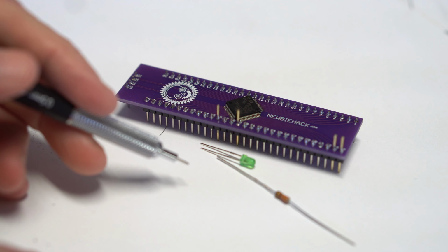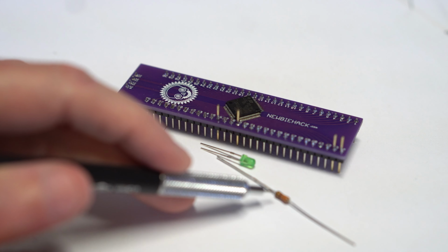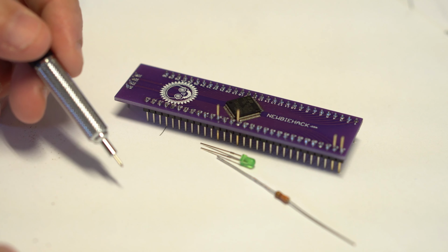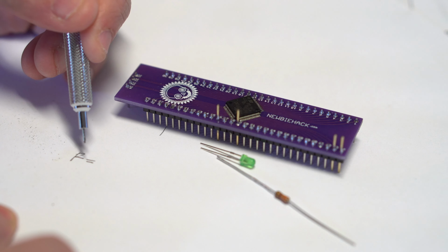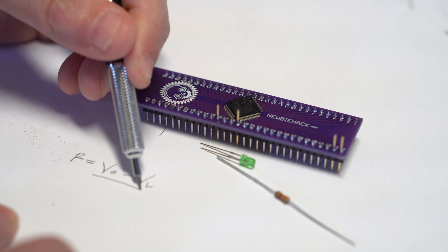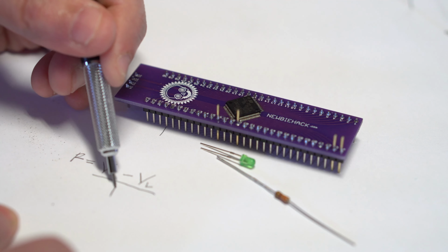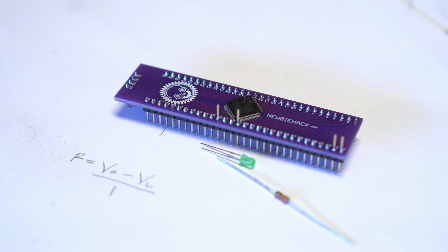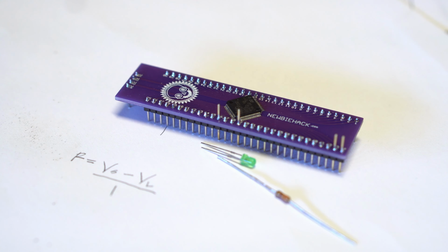If you want to figure out the actual resistor you need to use, you can figure that out using this formula. The resistance is equal to the supply voltage minus the LED voltage, which you'll need to know, divided by the current. I lost sound at this point, but if you use 0.01 amps for your current, which is a conservative number, the supply voltage is 3.3, and I use 2 volts for the LED voltage. You'll have to look at the data sheet for your LED if you are using a different LED. And my resistance value came out to be 130 ohms.